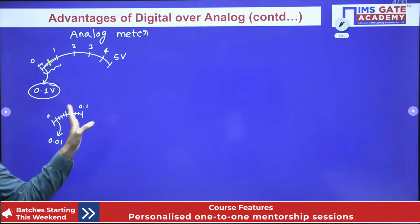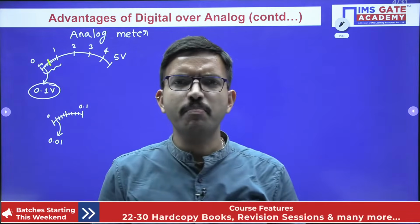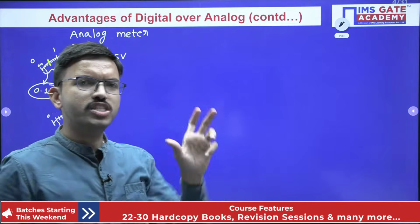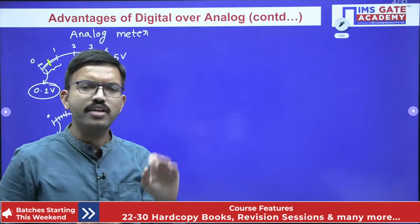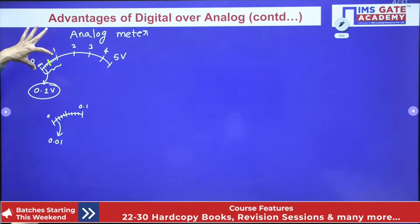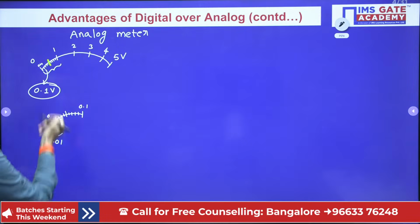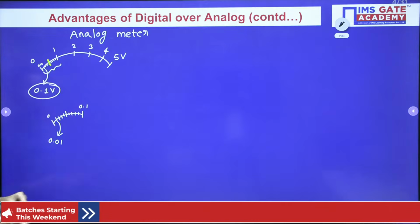This is called recalibration of the scale. Okay. Based on your requirement, according to which range you want the accurate value, accordingly you can change the scale. When you have a scale like this, it is difficult to note down the accurate value if the pointer is showing somewhere between 0 and 0.1.